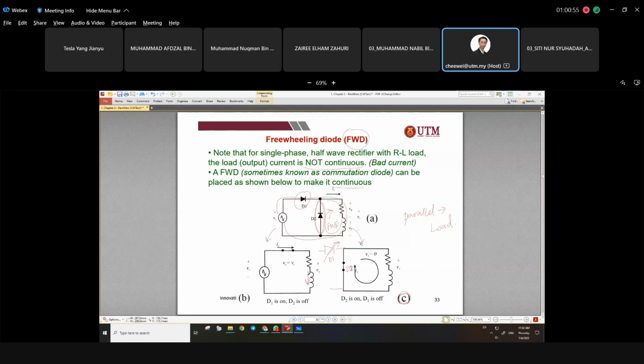So it's full already. So in the negative half cycle, this inductor is able to release energy. No charging, right? So what does it do? It will release energy. It's just like a battery now. So the battery will release energy and the current can flow. How does the current flow? Through the alternative path by the freewheeling diode here, D2. So D2 becomes conducting.